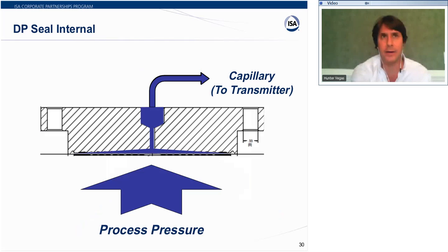That diaphragm is very, very thin. It does not take much to damage it at all. There's been a lot of cases where the mechanics forgot to put the gaskets on there, and they just bolted it up and they ruined them. It doesn't take much at all to ruin the diaphragm, so you want to be pretty careful with it when you hook it up.